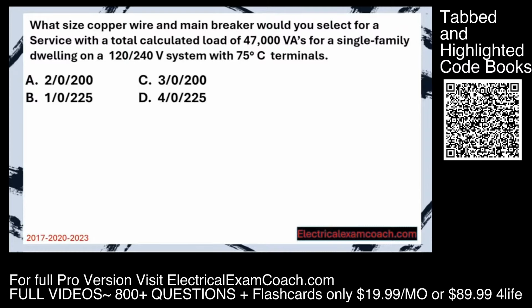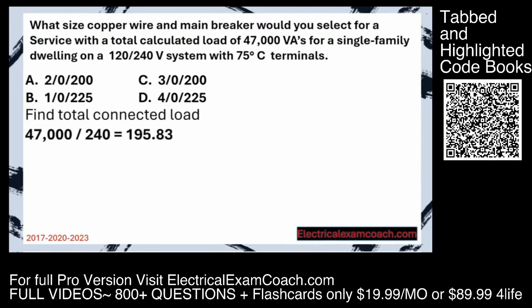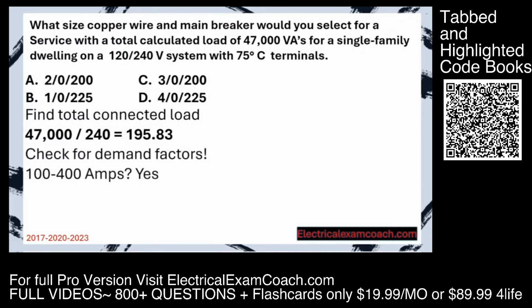What size copper wire and main breaker would you select for a service with a total calculated load of 47,000 VAs for a single family dwelling on a 120/240 volt system with 75°C terminals? Step 1, we're going to find our total connected load. In this case, they've given it to us, but we have to divide to get our amperage. When we do, now we can check for demand factors. And in this case, we do have a demand factor.